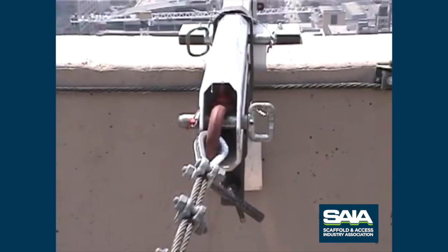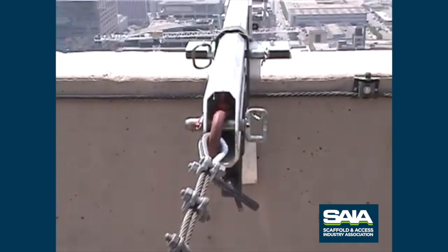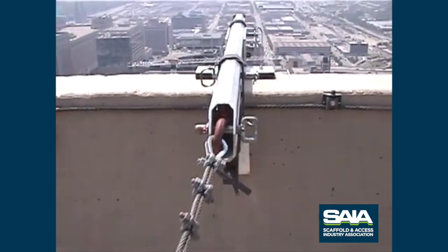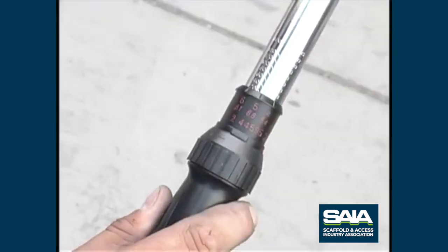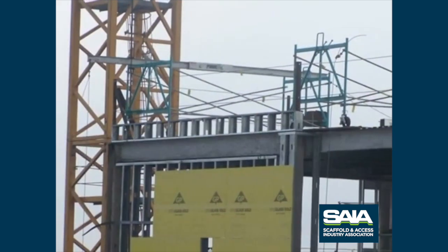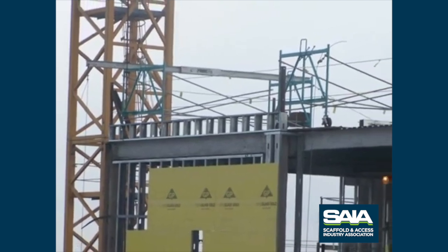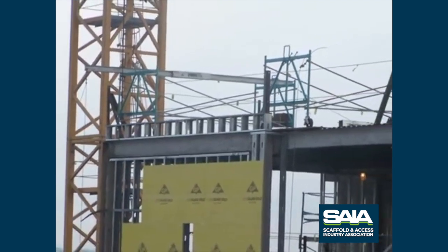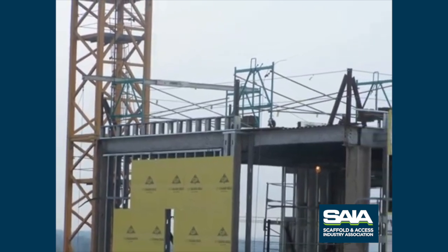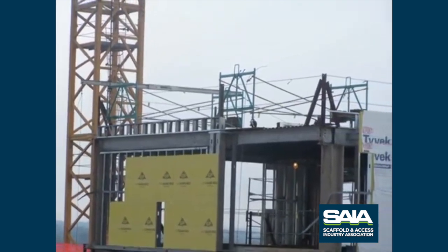A thimble and 3 J-clamps for 5/16 inch wire rope is used to fasten the tieback to the rigging device. Follow the clamp manufacturer's torque specifications and torque settings. The outrigger support frame must be designed for that purpose. The outrigger puts a concentrated load on the frame. If the frame header was not designed to support that concentrated load, it may fail.